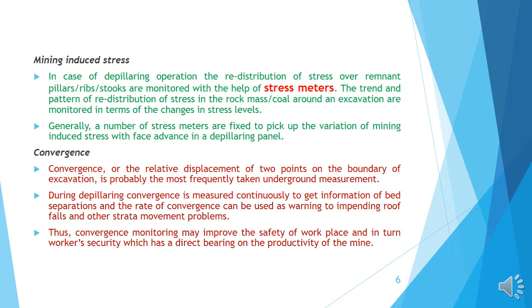First is the mining induced stress. In case of depillaring operation, the redistribution of stress over remnant pillars and rib structures is monitored with the help of stress meters. Stress meters are very important. The trend and the pattern of the redistribution of the stress in the rock mass around an excavation are monitored in terms of the change in the stress levels. Generally, a number of stress stations are fixed to pick up the variations of the mining induced stress with phase advance in a depillaring panel.